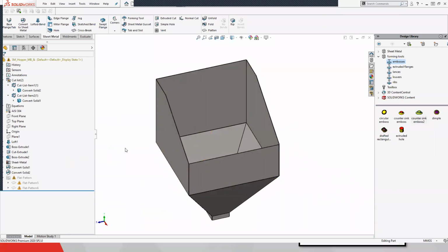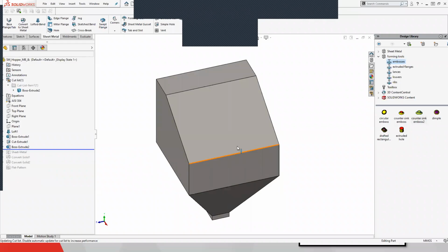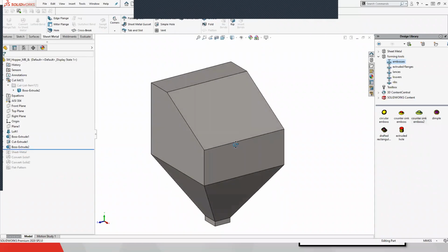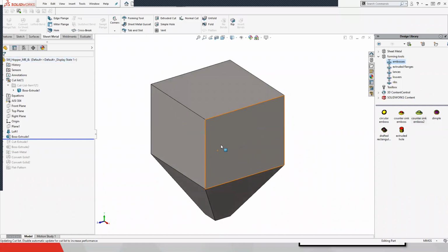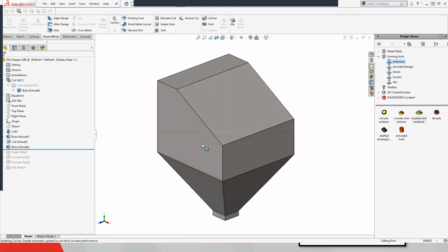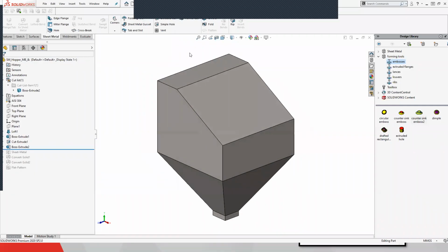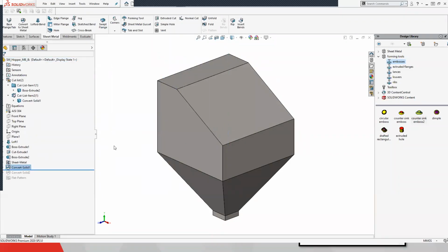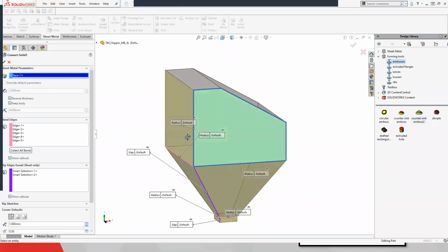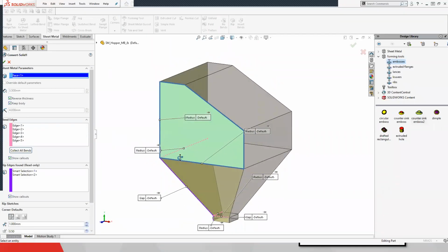So from here, you will clearly notice, or just to show you guys, I've gone in, cut and extrude this. Nothing really fancy, as you guys can see. Basic loft, basic cuts, basic extrudes. And then I've gone and opted for the convert to sheet metal feature. So just to show you, on the first convert to sheet metal feature in my tree, I've gone and selected the left face and all the abiding edges on the left-hand side.